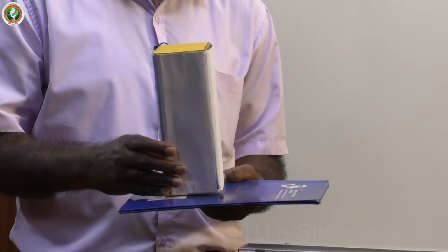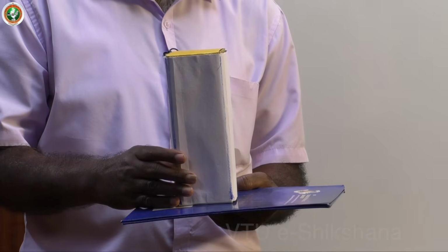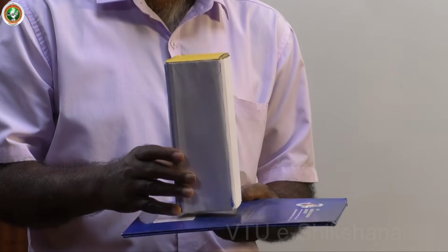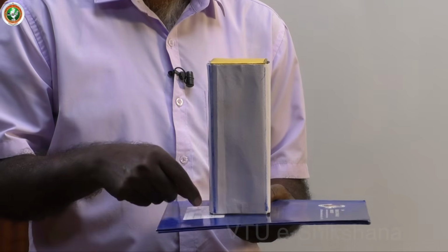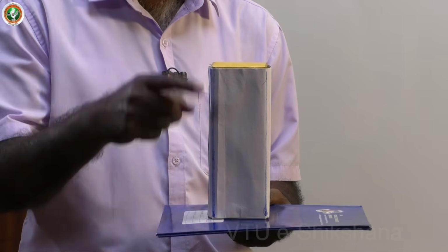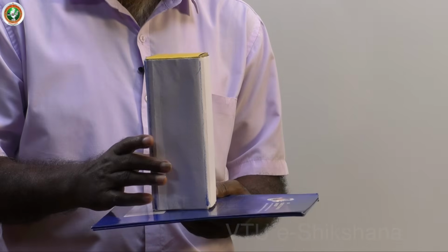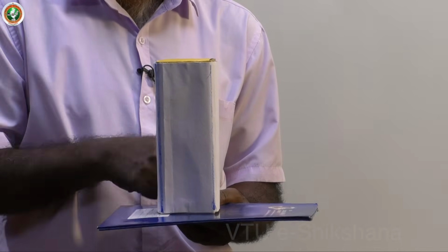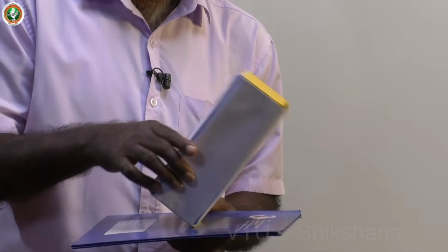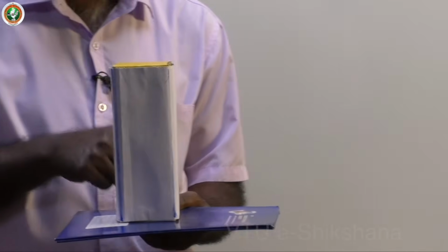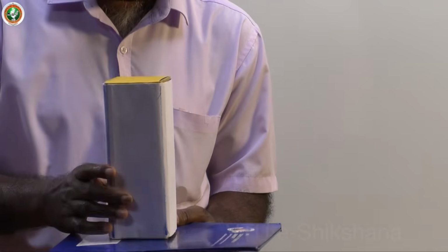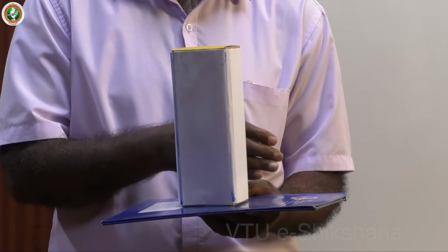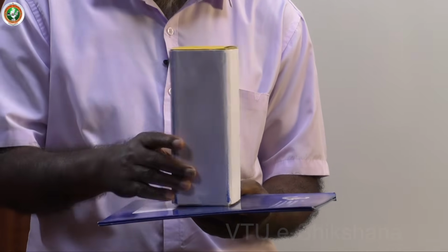Let me take the model and discuss this problem. We have the square prism of certain dimension, say 40 mm base edge and height equal to 65 mm. Now when I keep this on HP, the solid must have either edge or corner on HP when it is inclined. Now I have one of the edges on HP, so I keep the base edge perpendicular to VP. Whenever you keep an item on HP, if it is an edge, it must be perpendicular to VP. Then only you can rotate.